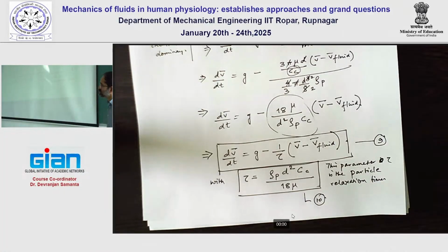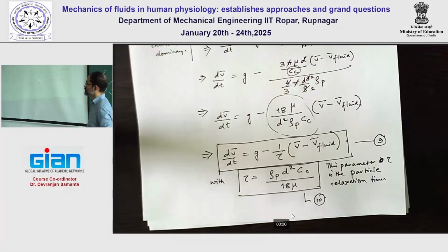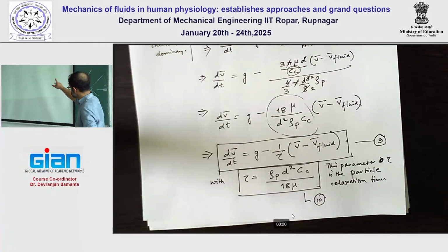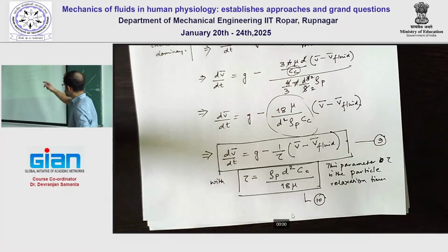So that is one way to think about the physical nature, but you can think about it in terms of other non-dimensional numbers as well. So I'll come to that in a moment. But this term by itself is very similar to the Stokes number as well. So Stokes number is a non-dimensional particle relaxation time in a certain sense. You just need to add some cofactors to this term, and it will become the Stokes number. Or you could use this expression to describe what the frequency is.